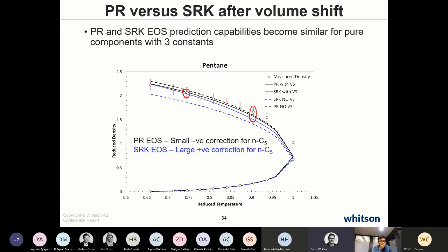Often we find it's not necessary. You can get reservoir densities within the desired 1 to 2 to 3%, and stock tank density is also within that same range. Occasionally we see that's not the case, and then we have, not the temperature-dependent volume shift, but a separate set of volume shifts for surface temperature and for reservoir temperature. They just have it as a function. So it's completely okay to have it. There's nothing inconsistent with it.